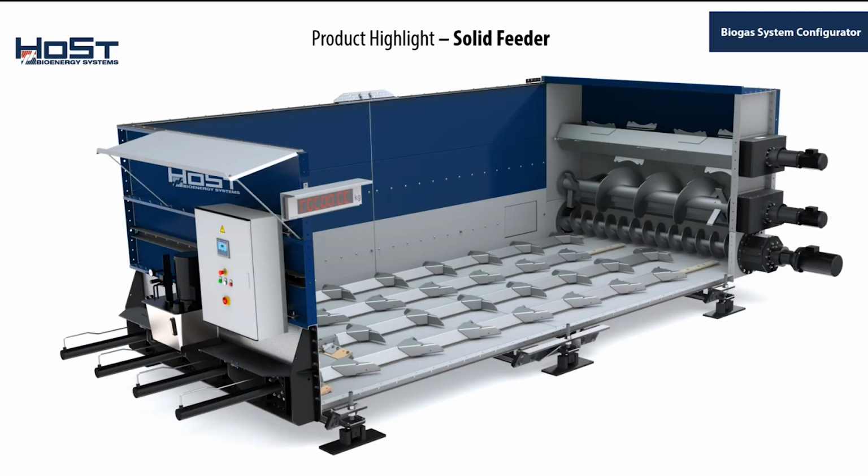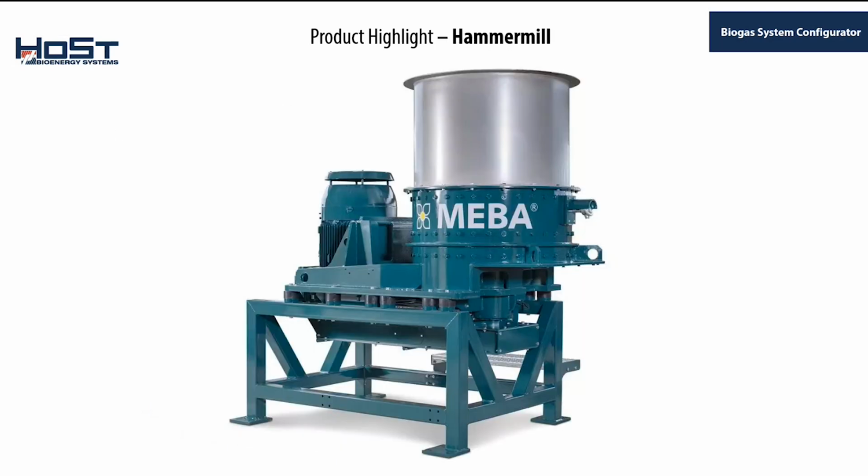So this is a very valuable cutaway. It shows physically what's going on inside the solid feeder. These push the material toward the feeding augers. There's 3 different types of augers that each have their own function, but this last auger takes the solid material and pushes it toward our second process, either the hammer mill or the blend unit, depending on the project.